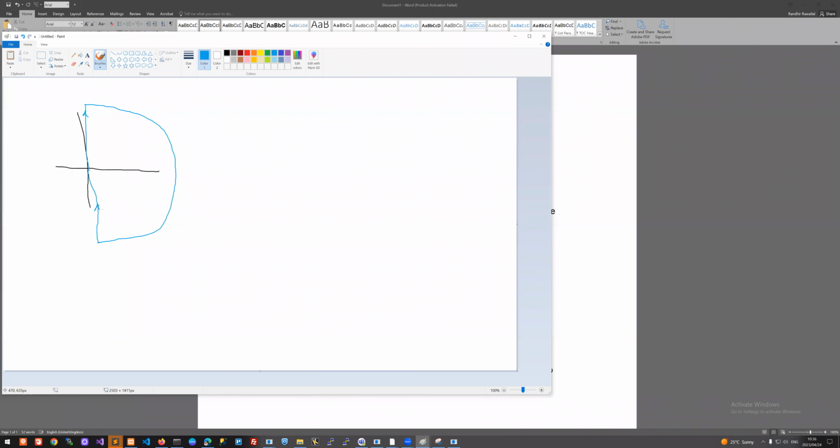And so we had said S equals I omega. We can get G along this line just by using our frequency domain function. And then here, the magnitude of S is going to infinity, and if that's the case, G goes to 0.